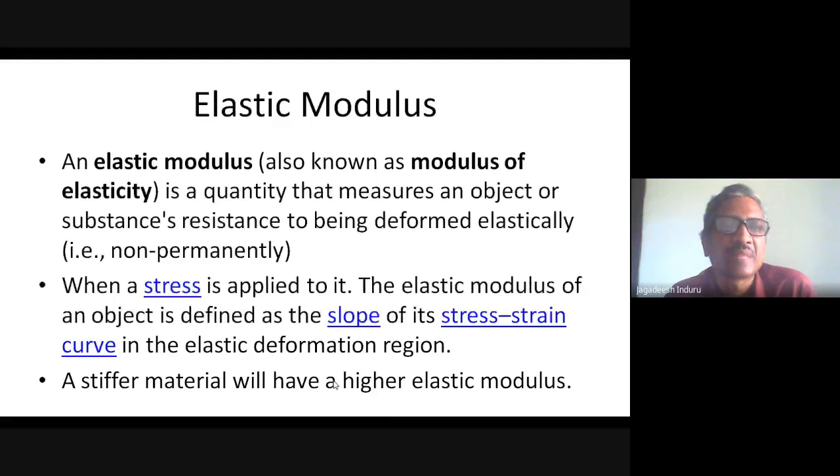It means if your pharmaceutical powders have a high elastic modulus, they will be compressed and become powder again after the upper punch is lifted, because they are not permanently deformed. They are temporarily deformed, and once the strain is relieved, the stress becomes zero and they come back to the original position without any deformation.